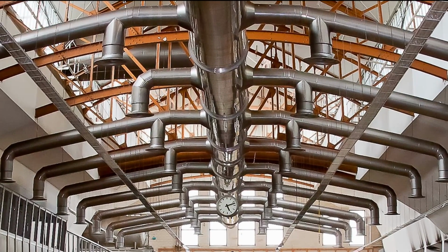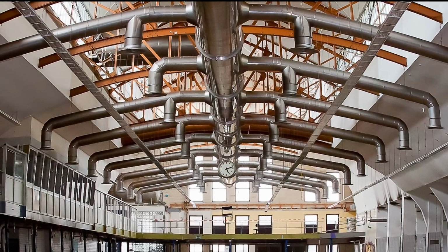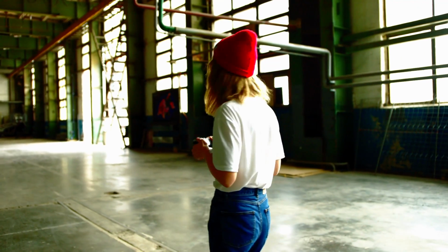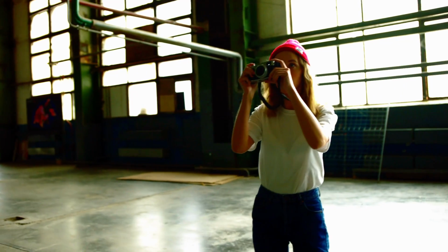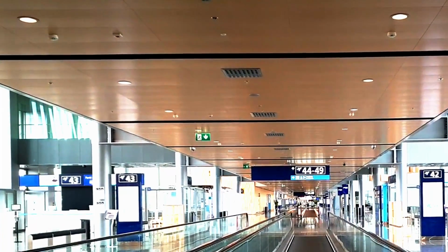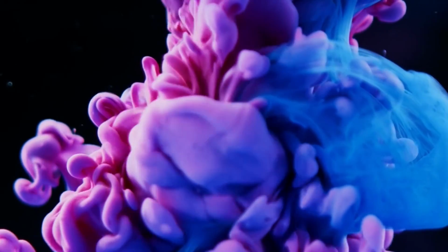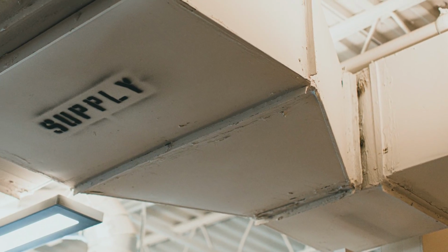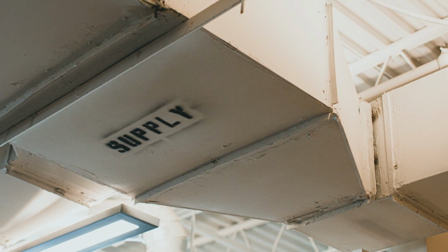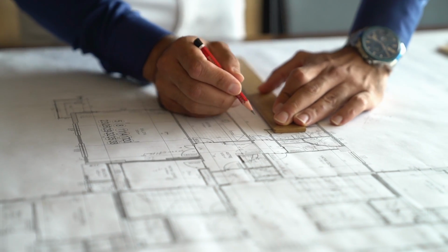Duct sizing can be like assembling a puzzle, where each section influences the others. It's necessary to carefully choose the dimensions of each section to maintain the air velocity within the established range. Furthermore, it's essential to be attentive to abrupt variations in velocity and area that may occur from one section to another. So, doing this manually, even through a spreadsheet, can be a bit boring.